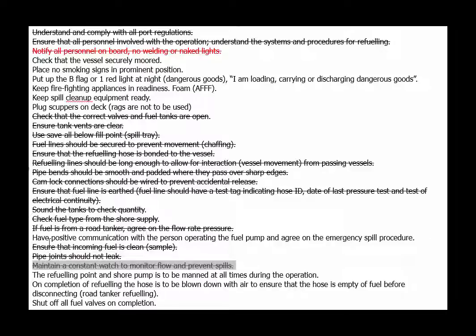So if we're using our standby person, we want them to be a competent person that's not going to disappear just because they get a phone call or a text. The refueling point is to be manned at all times, that's true. They can't walk off the job. On completion of refueling, that's on larger vessels, we blow through with air. And shutting all valves on completion, we do that.